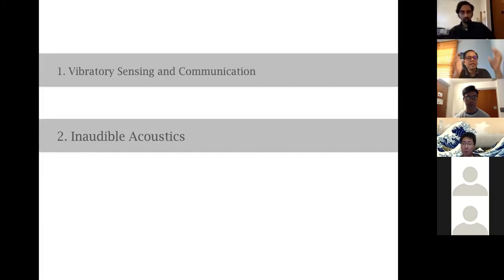What the receiver does is, the receiver takes the first bunch of bits, let's say 100 bits, and the parity bits are 10 bits. So you send 110 bits, and the receiver knows that the first 100 bits are what the transmitter is trying to send, and these 10 bits are parity bits. So the receiver takes the first 100 bits that it has decoded, computes the parity of it, and then checks if the parity that it received and the parity that it computed are the same or not. If they're not the same, then the receiver knows, oh, there must have been some errors in this decoding.